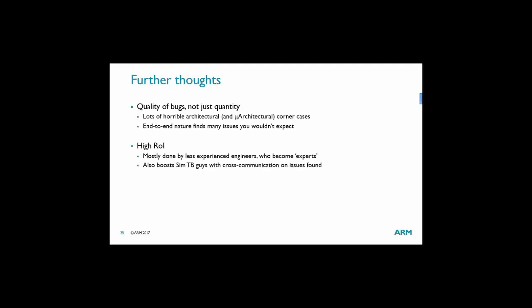As a further thought, the quality of bugs is really important. So it's not just quantity, it's the ones that are missed by the other verification methodologies that are never found by a simulation test bench or by vanilla formal methods, by the standard formal flows that we employ. And the end-to-end nature of the checks has meant that lots of issues that you just wouldn't expect to come out of certain checks have been found along the way. The return on investment has been very high. Generally speaking, across all the projects, we've had less experienced engineers do the ISA Formal work, who then become experts in their own right. They become formal experts as well as becoming ISA Formal experts.